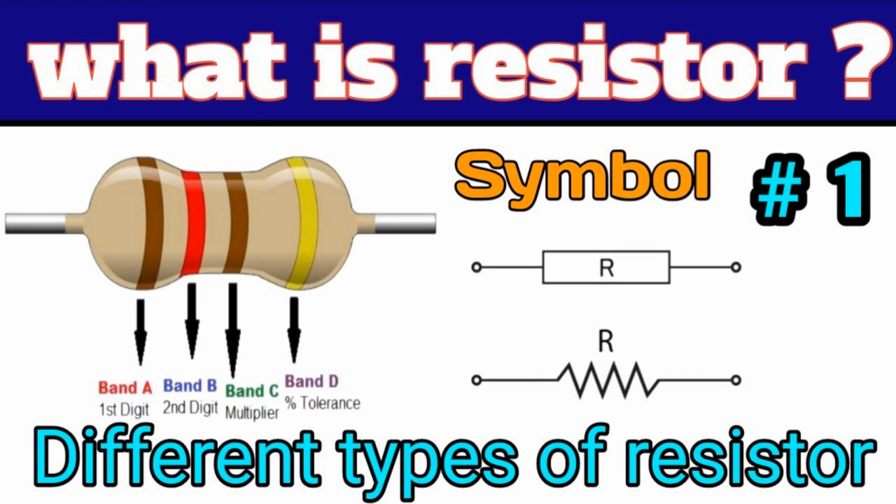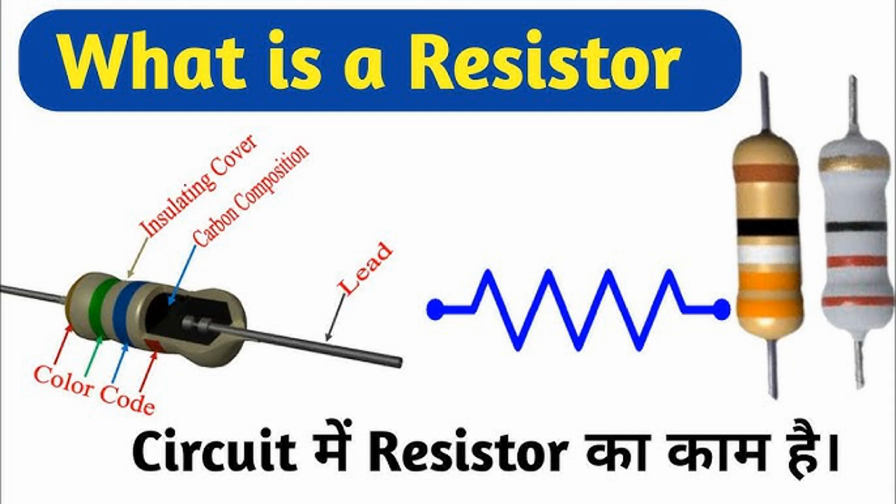High-pass filter, HPF. Purpose: allows frequencies above a certain cutoff frequency to pass while attenuating lower frequencies. Application: removing low-frequency noise, like hum, or allowing high-frequency signals to pass. Example: in speaker systems, a high-pass filter might be used to block low frequencies from reaching a tweeter.